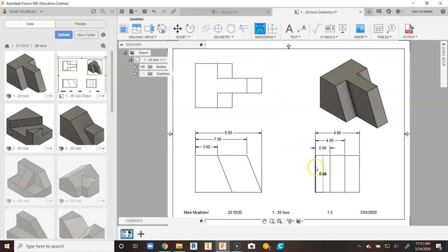Next thing, we'll do the height in our side view as well, because we don't want to cross dimension lines in our front view. Notice that if I just leave my mouse on top of a line, Fusion gives me a little bit of a preview, and I can just click, drag, and place, right click, and say OK. And notice that automatically it's going to give me an exact representation of what it'll look like once I click. Let's click on fit down here.